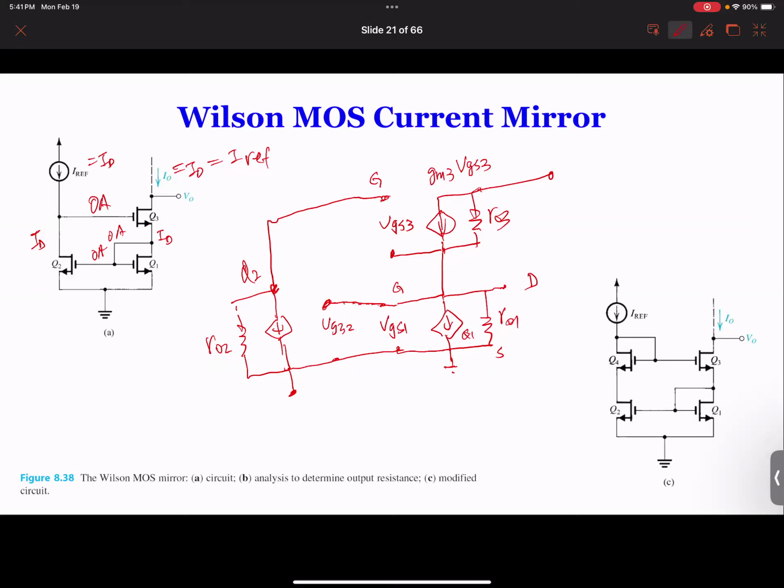So in this circuit, one of the things that we can do is again for Q1. So this one is GM times VGS1. If we convert that into a resistance, that's going to be VGS1 over it. So VGS1 cancels, so R is equal to 1 over GM1. So this one can be connected to a resistance.